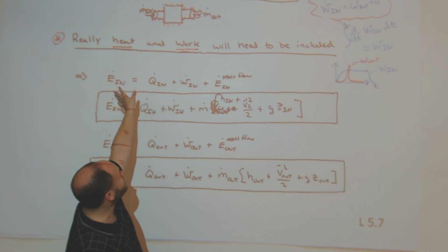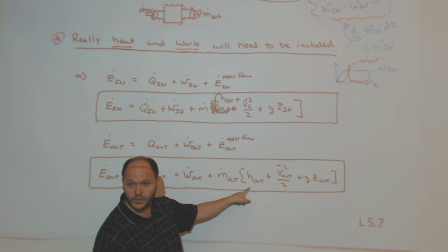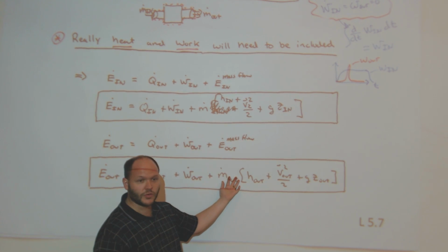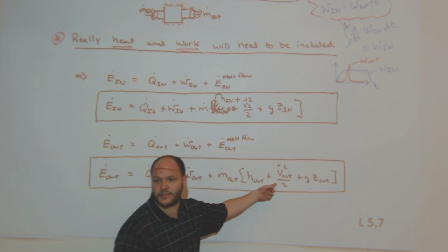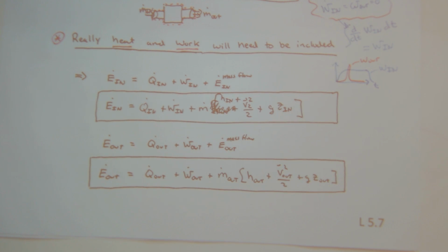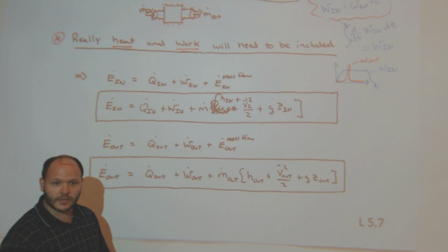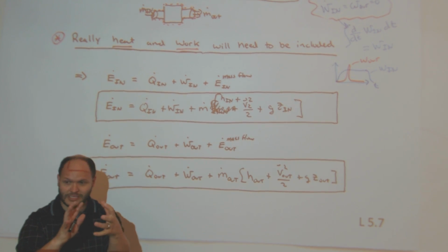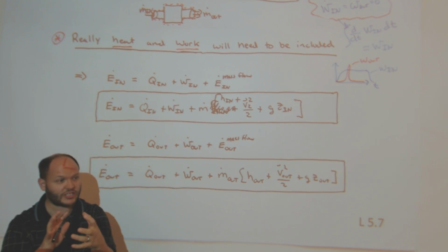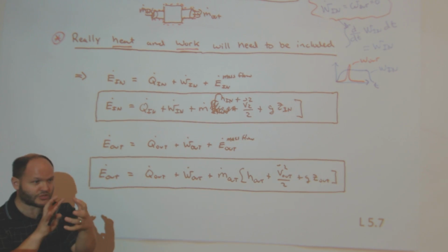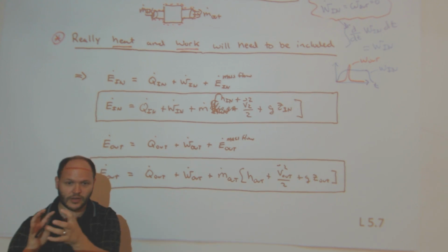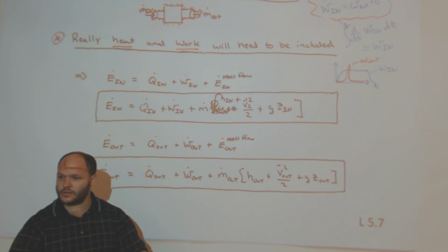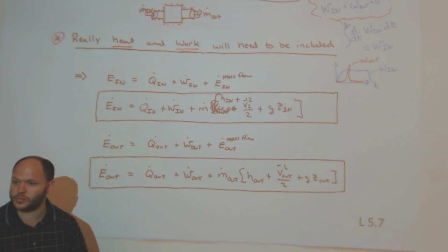And so under these main assumptions, we said the velocity was 0, or v dot is 0. All we said, we just broke it down to a mass transfer rate in. So it simplifies to this. So the time derivative of the height of the output isn't changing in time. I don't have that picture up, but the mass coming in, the control volume, the temperature within that control volume of mass coming into my system isn't changing in time. The pressure within isn't changing in time. So all I have to look at is the velocity and the mass flow rate and its average thermodynamic temperature, thermodynamic pressure, density, or the inverse of that, specific volume.